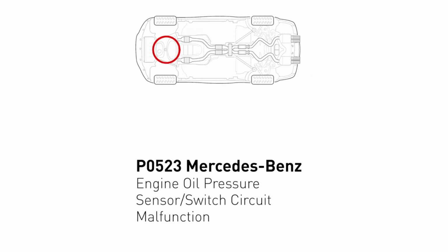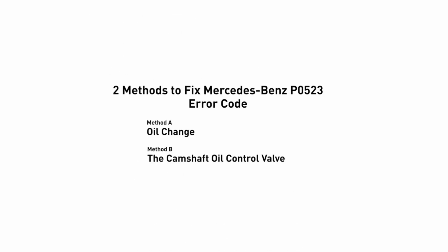It indicates that the engine computer reads a signal from the sensor that is either too high or too low in relation to the manufacturer's parameters. Here are 2 of the most practical solutions to fix Mercedes-Benz's P0523 error code. Method A. Oil change.